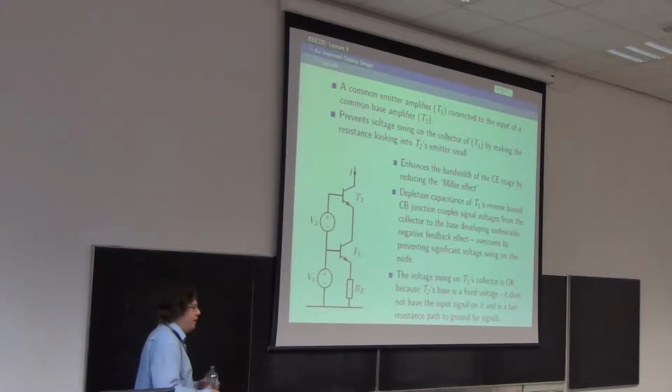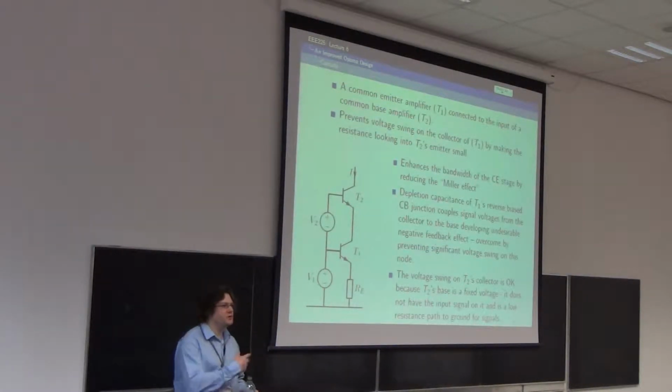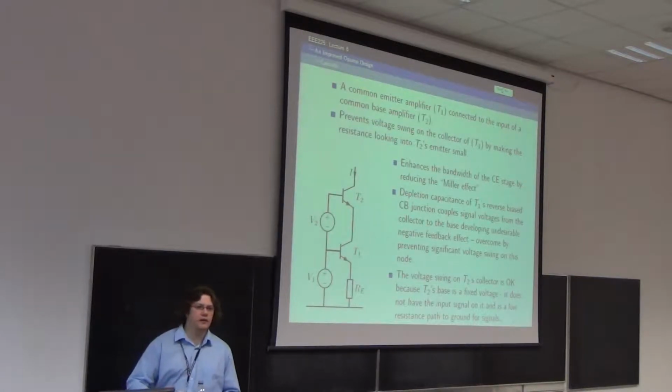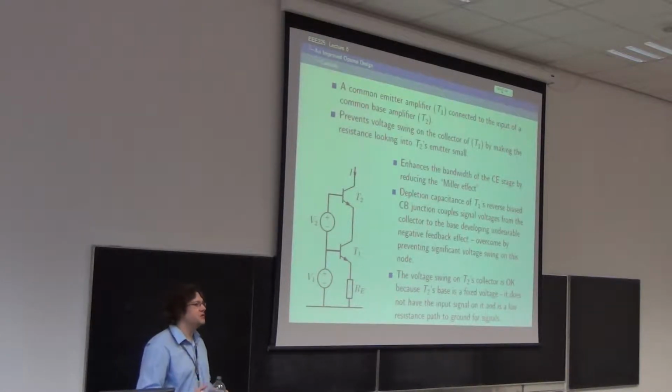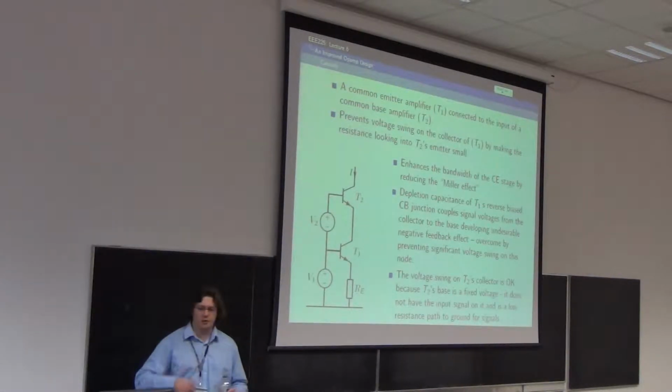But I couldn't put everything I wanted into one op-amp, because there are lots of ways of doing all the individual bits. There are 3 stages. I could have had an output stage that conducted for 360 degrees of the cycle and only used 1 transistor if I'd chosen. Power dissipation would have been a lot bigger, but that's by the by.